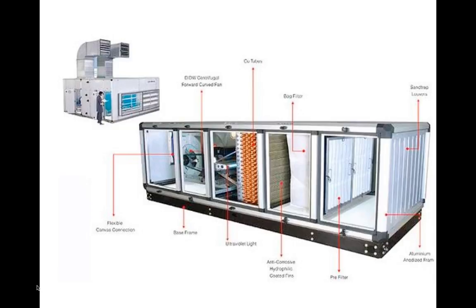You see these bright copper tubes. There's another one next to it, behind it, that is made out of steel, where you can't see the bends so easily. One of those is likely to be a steam coil for heating. The other one is a chilled water or a refrigerant coil for cooling. It might have Freon in it or might have cold water. So those two coils are the way that you control the temperature of the air.